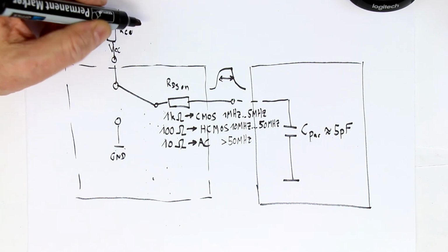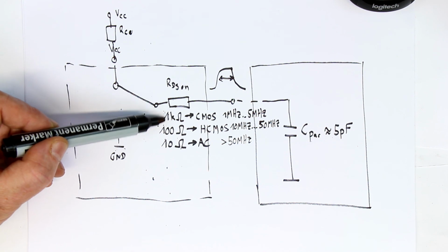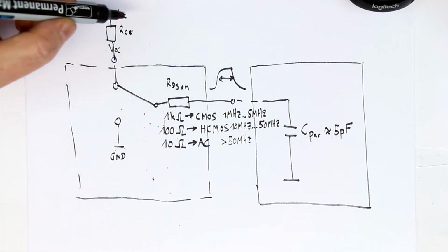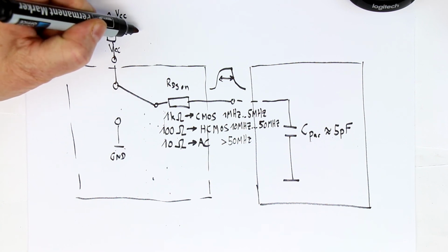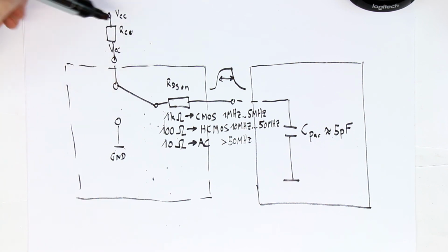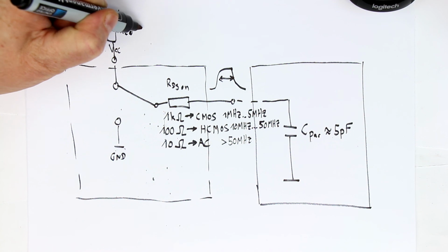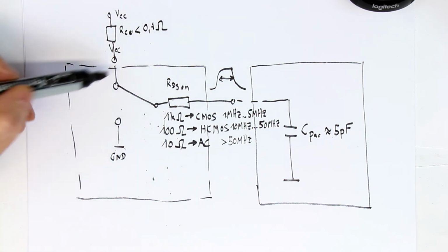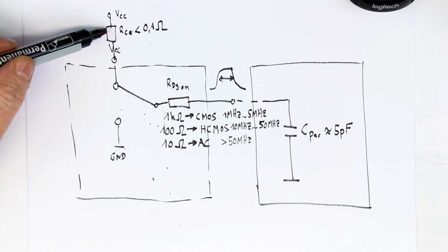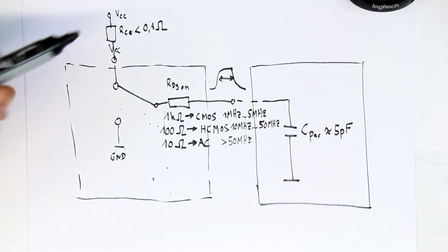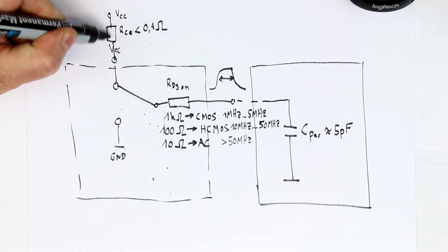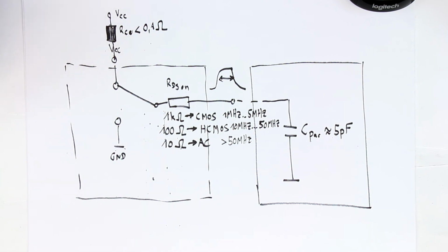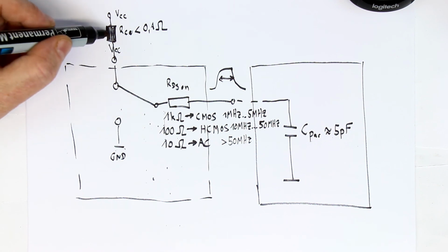No, look here, we have resistance in the range between 10 milliohms and 1 ohm, and you really have to make the worst PCB layout to get this as high as 0.1 ohms. So the copper resistance never plays any role, but each PCB trace is always an inductor, and that's where the problems come from.